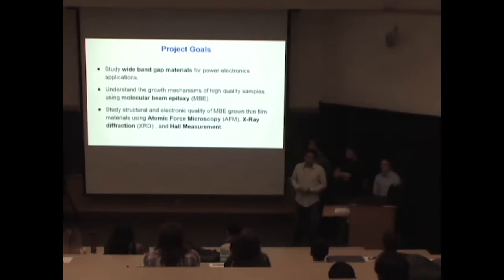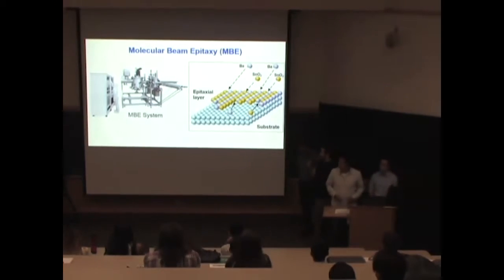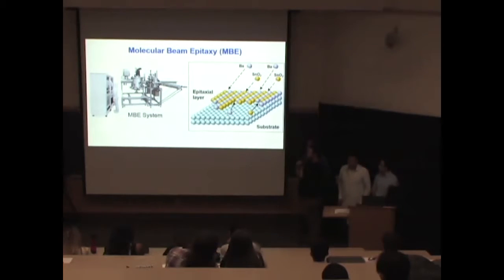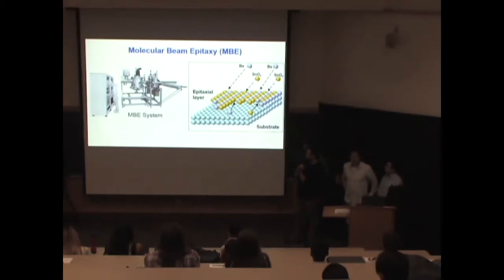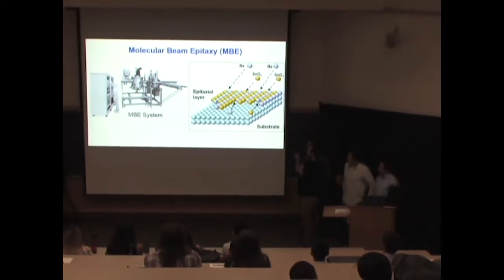So our goals for our project included studying this material for power electronics applications. We also sought to understand the growth mechanisms required to grow this material on the MBE machine, or molecular beam epitaxy. And next, we studied the quality and electrical properties of this material using 3 known tools: atomic force microscopy, the Hall measurement, and X-ray diffraction. Well-known tools.